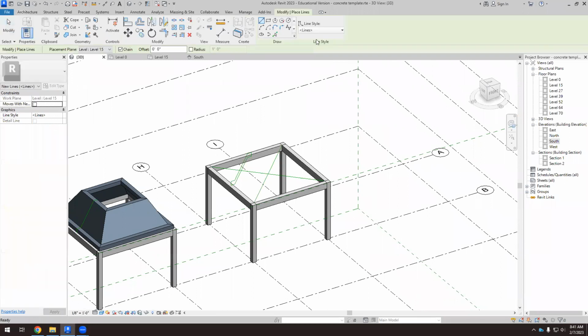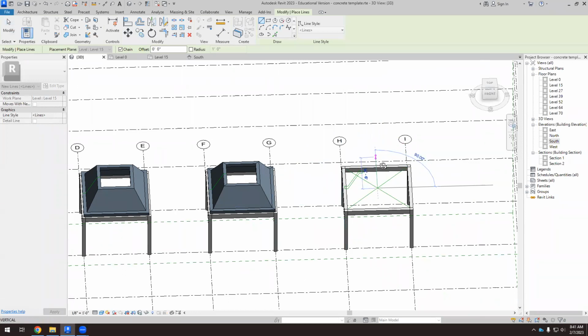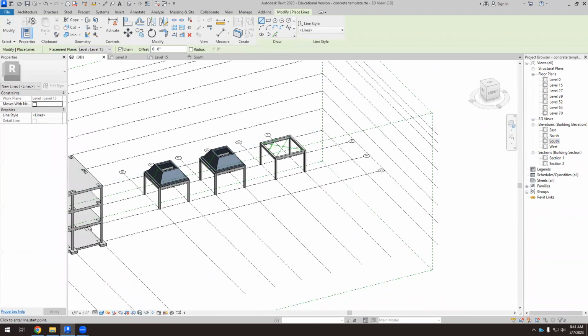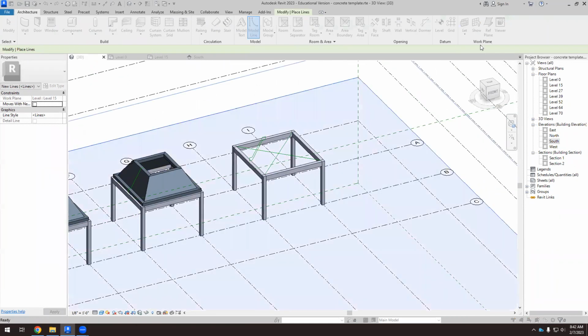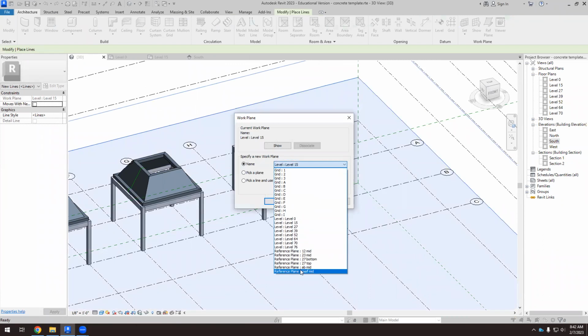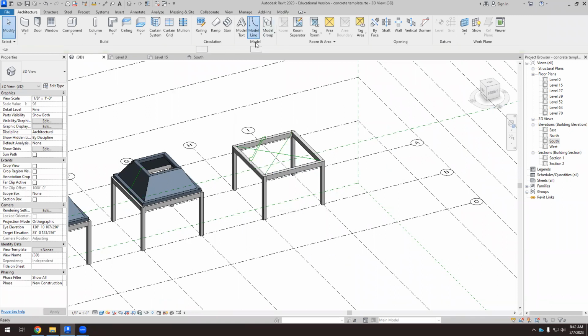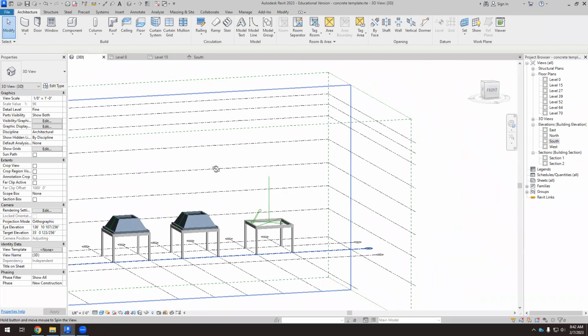I have to draw model line. It's there, but you see what happens here. I can create a. Okay, so that doesn't work. In architecture, before doing the model line, I have to set the work plane on this roof mid. And now if I draw a line, that line will be vertical. Okay.